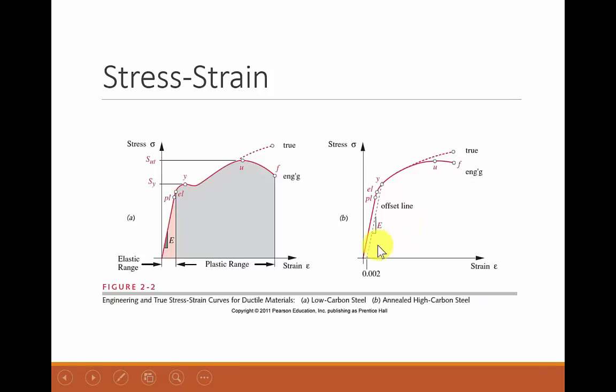For very brittle material, you never really get a warning. Yes, you do see a decrease in the amount of strain, and if you were to ever take the stress back off, you'd realize that you've now permanently deformed your part. So you've crossed into that plastic region, but the only real warning from just looking at the part happens right here when it actually fails. Now this is not a good situation. No one wants to know your part is failing when it all of a sudden snaps. You want to be able to look down there and see that it's got some wear or something like that.